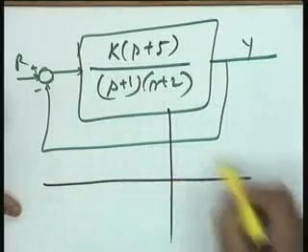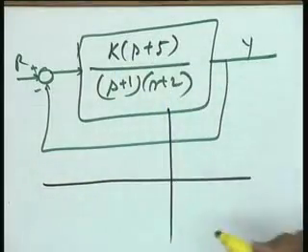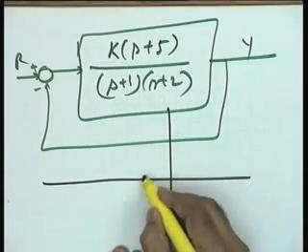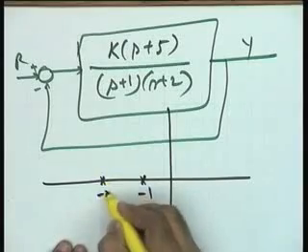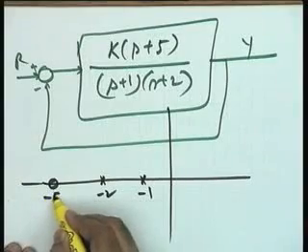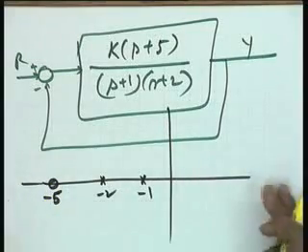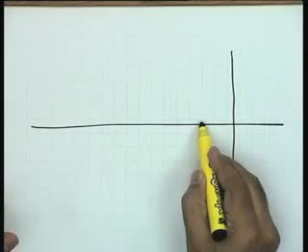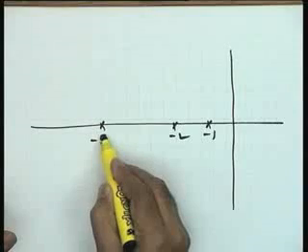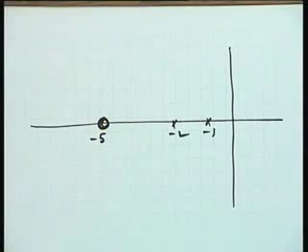Let me make it here itself, though there is an overlap. But since these poles and zeros will be available to me here, I make a sketch here itself. S is equal to -1, -2 and a 0 at -5. Please see, zeros I will represent by a circle. It is not to scale, or let me make it a little more appropriate. If not exactly to scale, it should make some sense. -1, -2, -5. 0 by a circle. So, this is the situation.